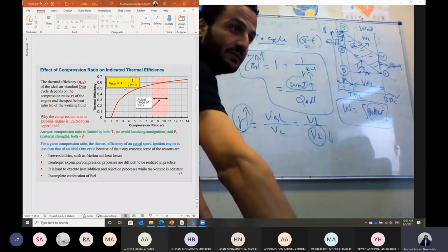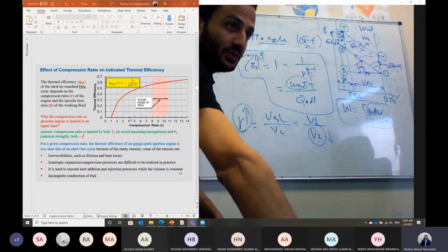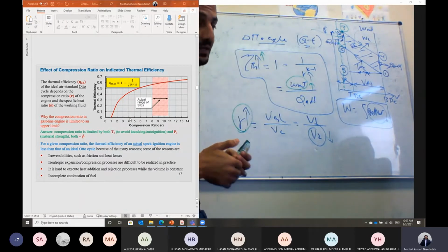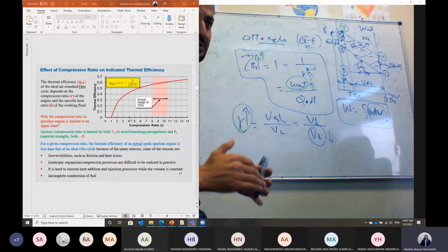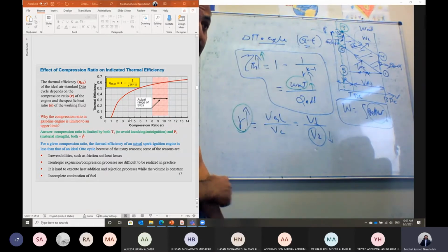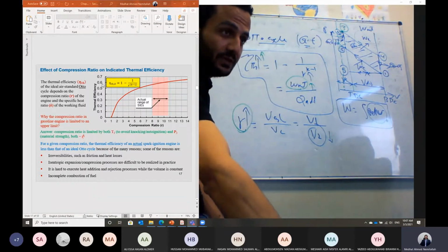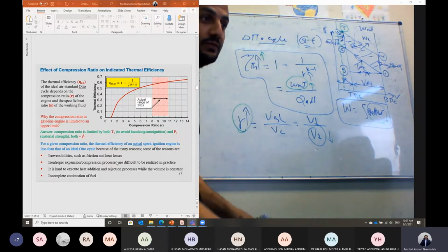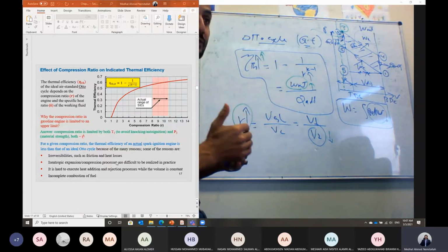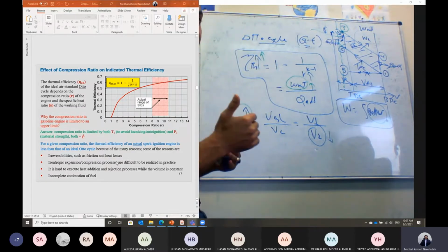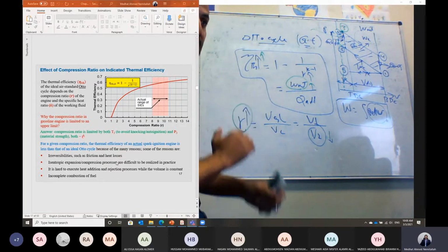That can result in a thermal efficiency of the Otto cycle of about 60%. But as you know, guys, this is not the actual efficiency of a gasoline engine. Usually the efficiency of a gasoline engine is about 30 to 35%. This is the maximum efficiency of a gasoline engine. But for the Otto cycle it can approach 60%, because in this cycle we assume all processes are reversible. We don't have any kind of losses. We assume we don't have intake or exhaust valves.